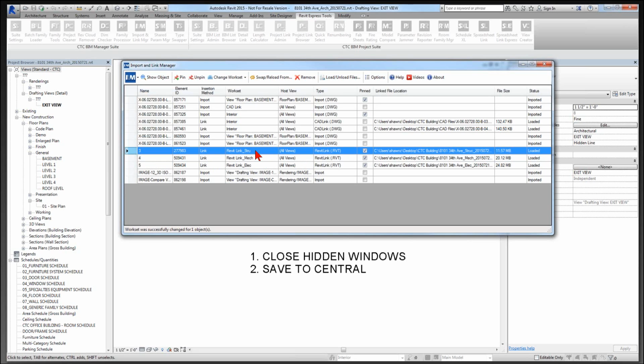It should be on whatever the main work set is, probably for the main link itself, or possibly it might be on an interior architecture work set, or maybe a level by level work set, depending on how you break out your actual building. Maybe you've got a level 1 interior architecture work set. If it's a huge model and you need to micro control what's open and what's not, you could potentially do that. You can use this to see what the instance work set is.